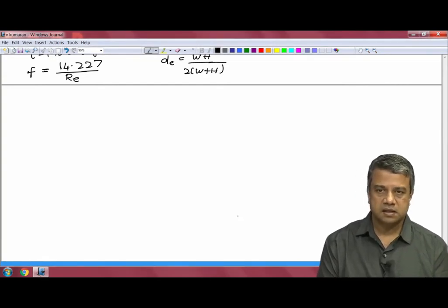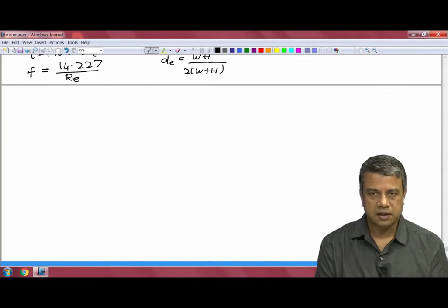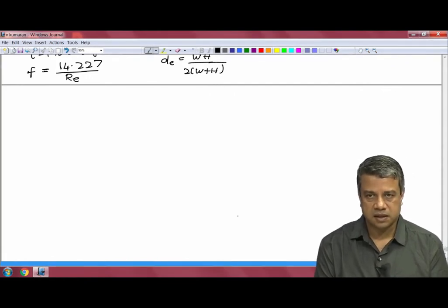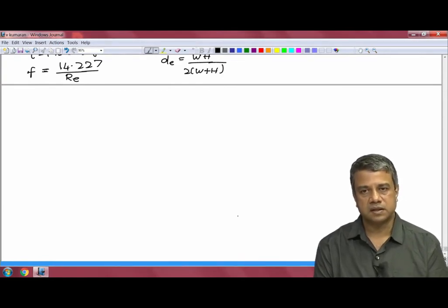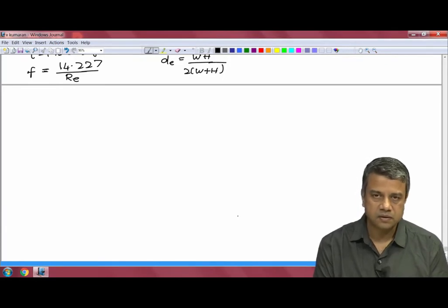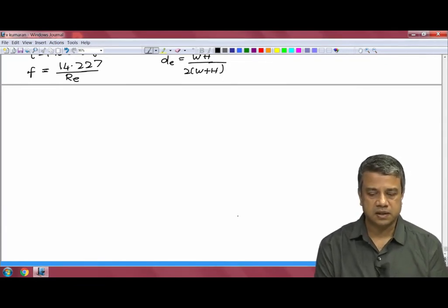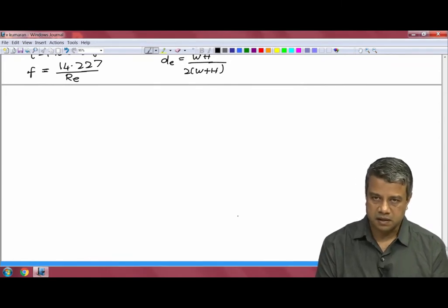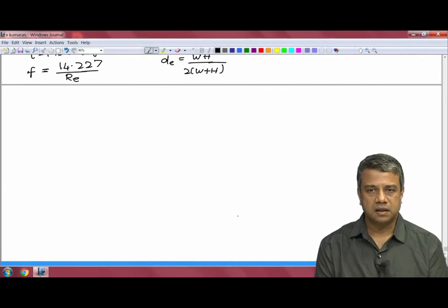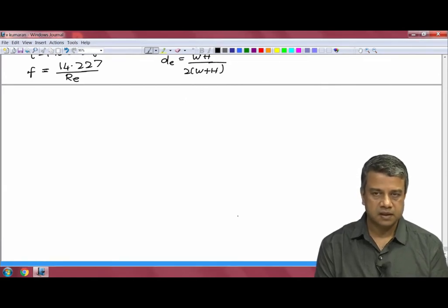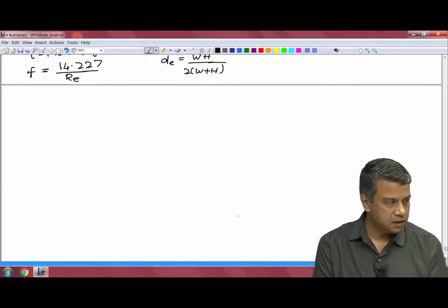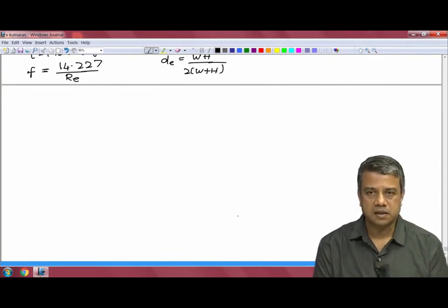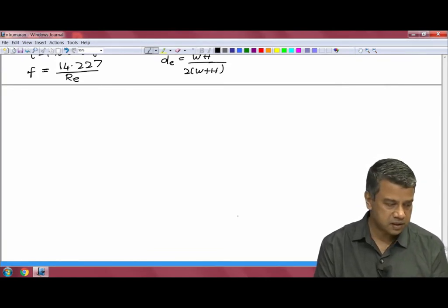The second case: homogeneous boundary conditions in all directions, in the y direction and the z direction for the velocity, forcing through an inhomogeneous term in the equation itself, that is the pressure gradient. And how to use that forcing in order to determine the velocity field, the flow rate, the average velocity, and from that the friction factor. Okay. So, with this we complete our discussion of separation of variables in a Cartesian coordinate system.